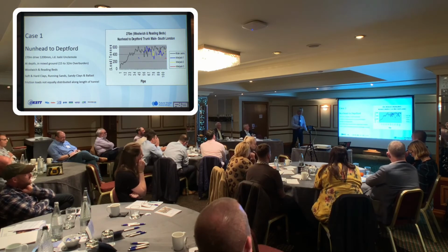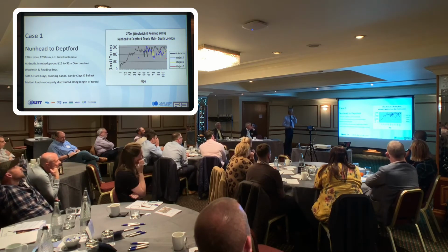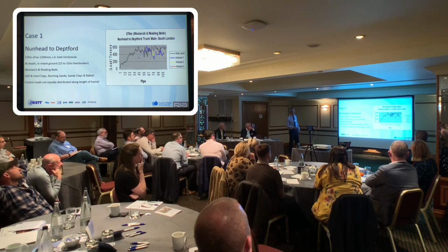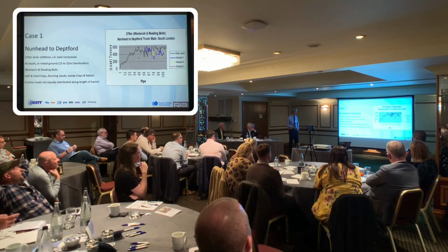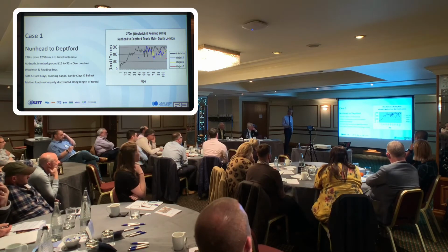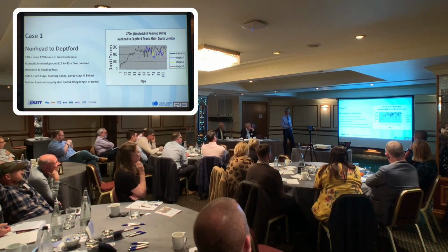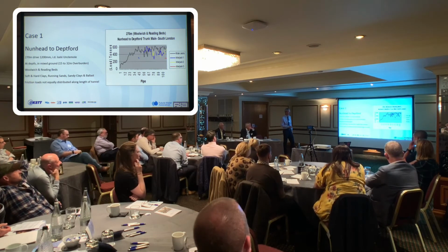So just to illustrate, I've got a couple of different examples. These are quite old jobs because they're from an old presentation. So this is a project in London on the Nunhead to Deptford Millennium Main, which was supplying a water main to the, what's it called? The big tent. The Dome, the Millennium Dome, that's right. So it's a 270 metre long drive, it's a 1200 ID slurry microtunnel.